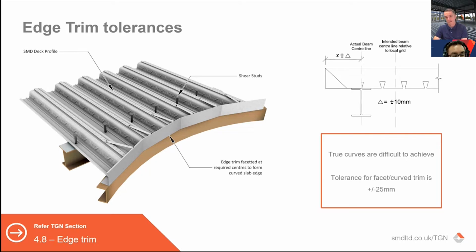Is that we can also install to engineered positions. So once the beams are installed and the deck is installed, an engineer will then go round, see where the theoretical grid lines should be, and we can then do measurements from there to ensure that you're reducing the tolerances involved and not ending up with a compound tolerance of the beam and the edge trim. But that's only where that kind of edge position is really critical for maybe the facade that's being installed or whatever.